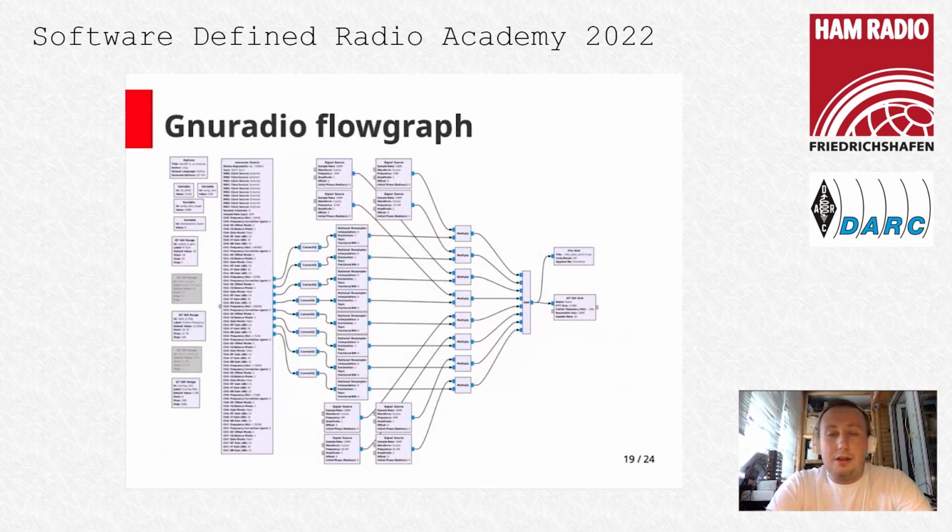So yeah, the first revision of the software was totally a GNU Radio flow graph. You can see it on the screen. I used the Osmocom source to get the signal from the HackRF boards. Plus, I had to patch this block additionally, so now I can use 1 PPS synchronization. Basically, I had to add a call of one function, which enables synchronization on all boards.